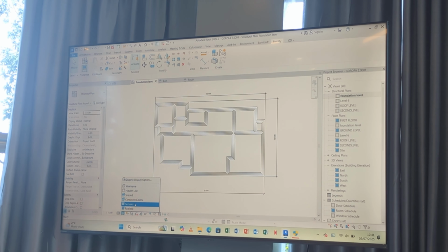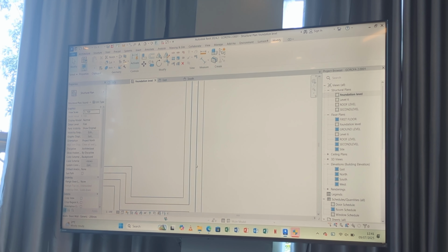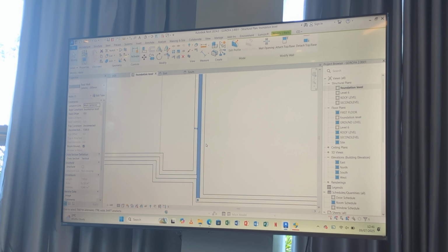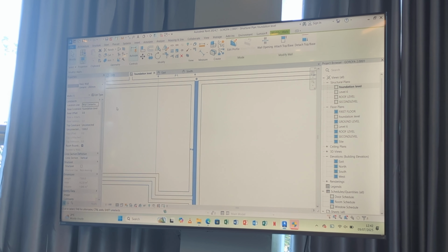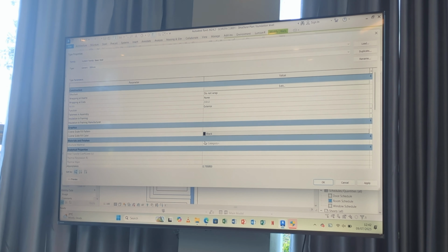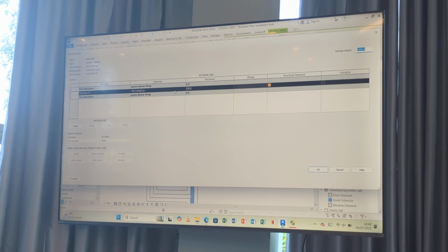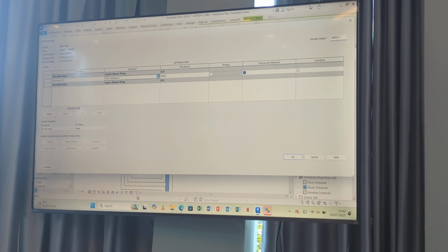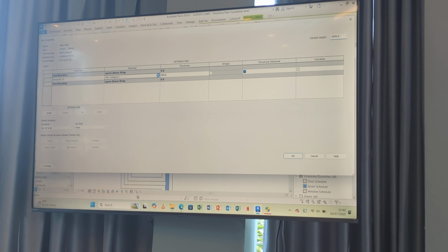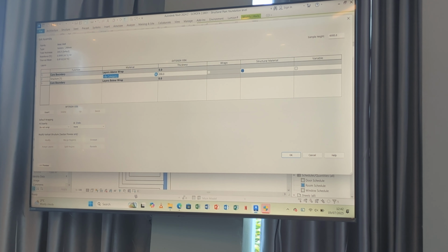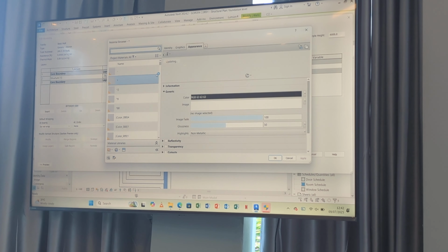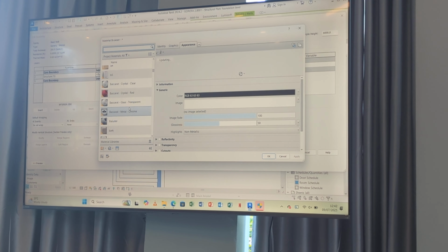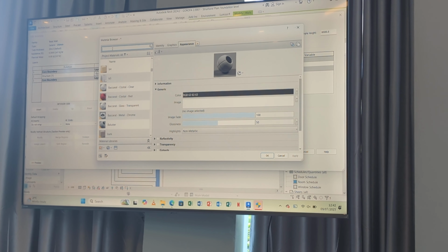Okay? You can leave consistent colors or hidden, but now you have to give those materials to be visible. Okay? Remember here I'm seeing from the top. Here I don't have any material, come edit. Come give it block or brick or whatever, and then give it its hatch. Such that when I'm seeing it from the top, I can see the hatch, and I differentiate the brick from the concrete strip. Are we good?